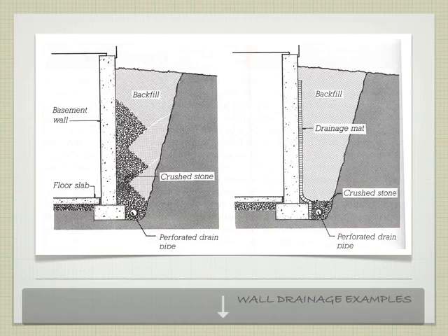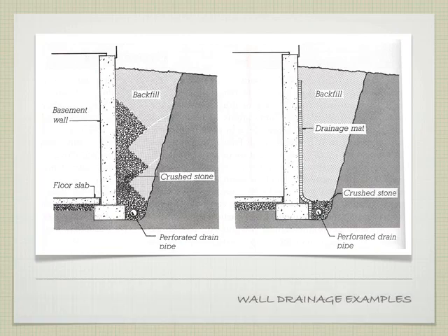So we have to move from that into the idea that water can somehow percolate into these foundations, and we have to deal with water. Water is always a problem. And so in this particular case, this is with a basement inside. There are a variety of ways of trying to drain out water, because water's naturally going to try to come in, okay? So something like this. This was our original excavation. By the way, given this angle of repose, what kind of soil would it be? I just said what it was.